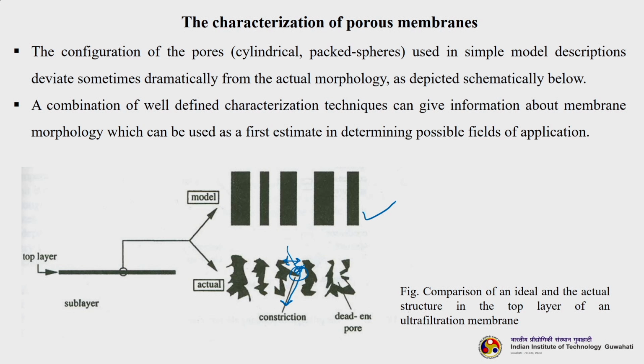So, after some time this particular pore will be of no use. It becomes just like a dead end pore, and it is not contributing to the permeation. A dead end pore is one in which the pore is actually sealed at the bottom. That means anything that is coming is getting deposited inside this dead end pore.